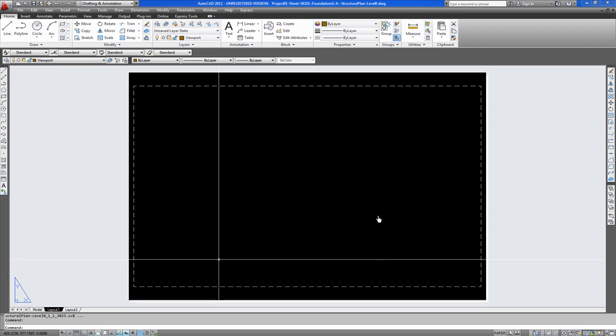Now we will be printing this model to scale, so you double click into the model. Like I said earlier, this drawing was originally scaled to fit at 1:200 on an A1, but we will zoom it at 1:500. It should fit to scale at 1:500 on A3. There you go. Just show that again. Zoom, it's 1:500 XP. And there you go. Now in this case it fits perfectly on the A3 sheet at 1:500.